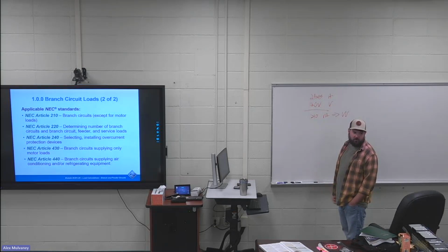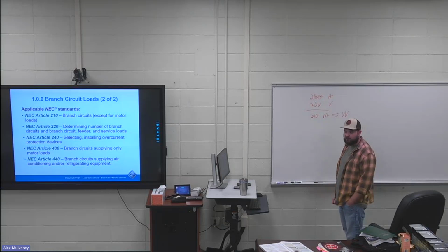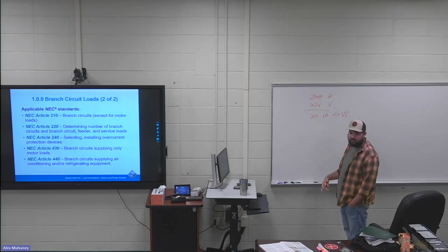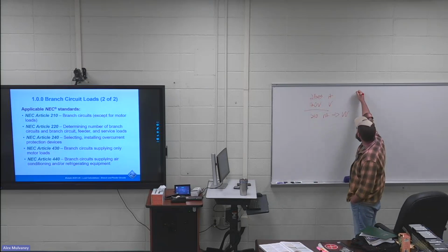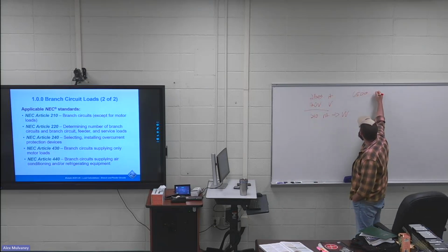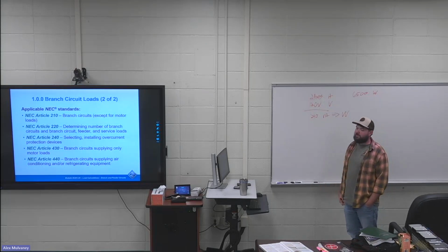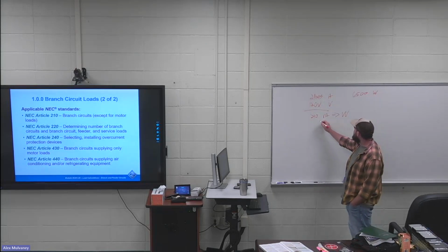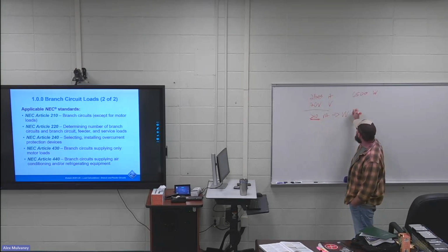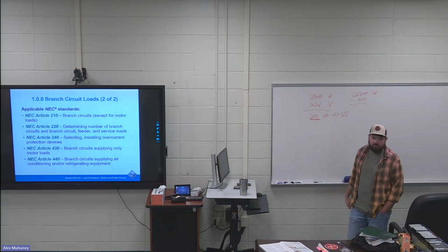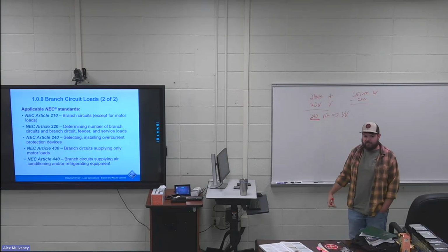So y'all have used generators before at your house when the power goes out, or at least heard of people that have used those. A pretty common size generator, like just going and buying one from Home Depot, is about 6,500 watts. So this is all load calculations. If my toaster uses 240 watts, I'd have to go in here and do your calculations to see what that generator would actually run. So that's how you size what size generator you need for your house.